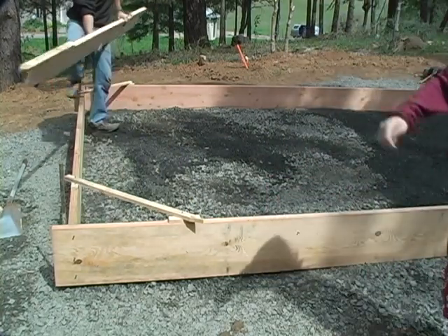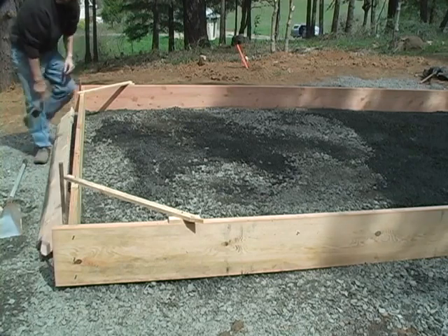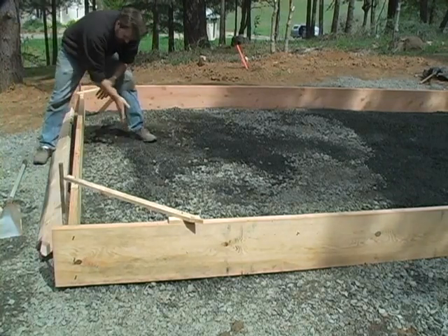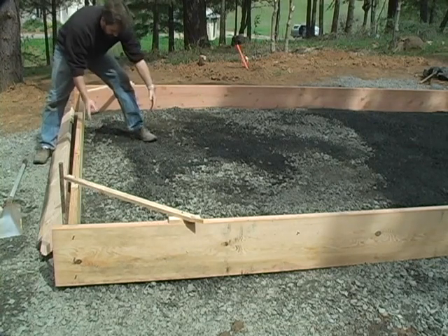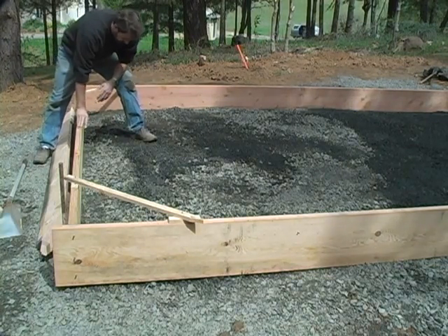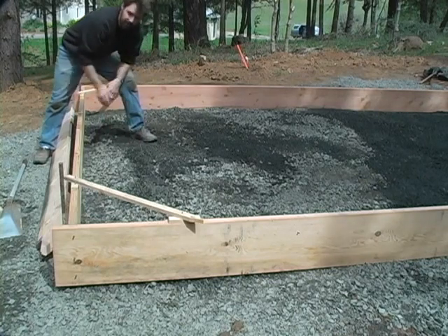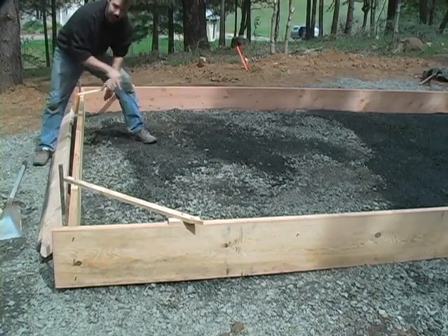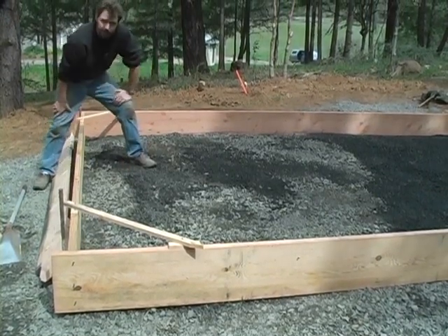Now around the edges, we don't have to worry too much about bringing the gravel all the way out because we're actually going to cut this out for our footing with the square shovel once we've got this in place. So we'll have a wide footing on this building. So we won't worry about this. You want to go a little bit further than the width of your footing will actually be, so you can compact it and then cut it back out. You don't want the loose material to be sitting right at the edge of your slab.